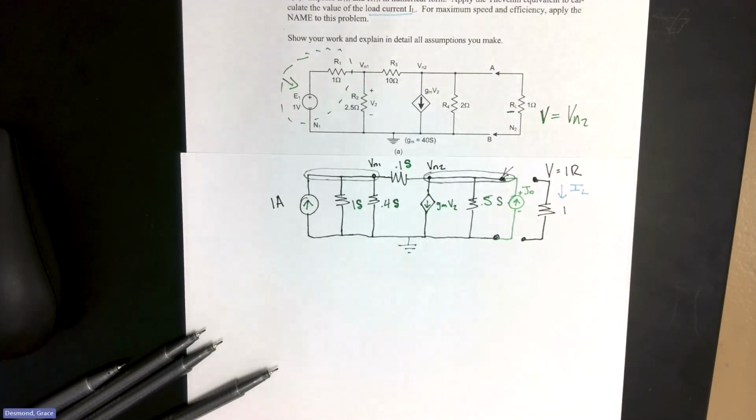If there's no current, that means that there's nothing there. There's no connection because there's no current. That's why it's an open circuit. Same with 0 volts. If you have a wire and you tried to measure, is there a voltage difference over this wire? There wouldn't be. And so that's why a 0 volt voltage source, a turned off voltage source, just acts as a wire. And that's going to be really, really important, especially for your switches.